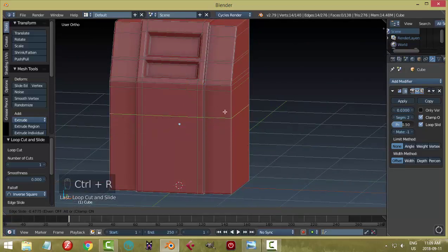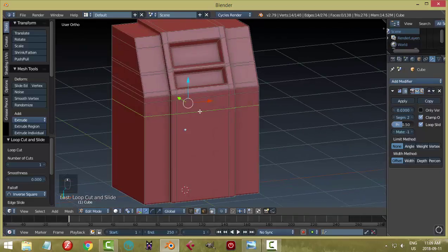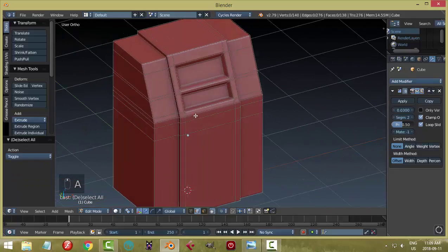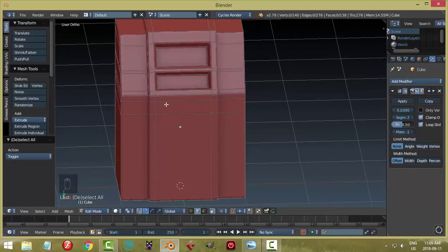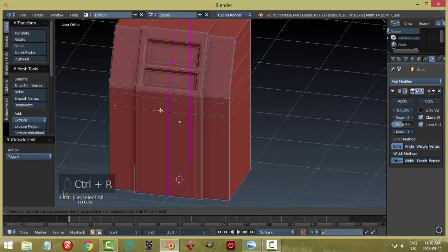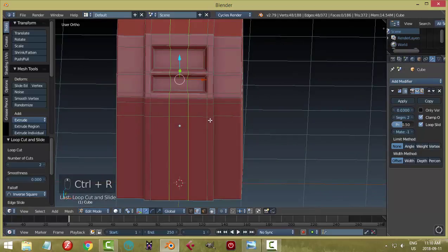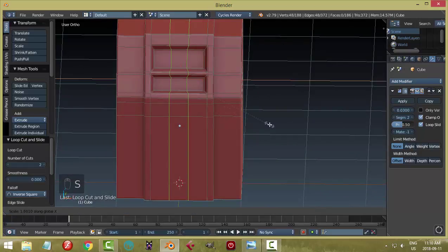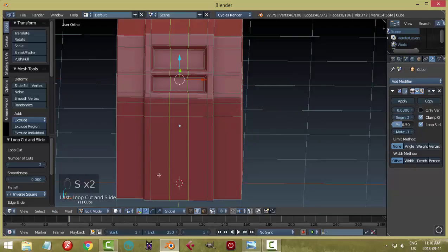Let's go Control R and put another one and define the height of this thing that we want the money to come out of. It might be a bit exaggerated here. So we're going to have a space here, but I want to have a little partial rectangle that goes all the way around, then a little hole. So I'm going to go Control R, roll my mouse up. I'm going to get 2 edge loops, SX. Oh, now that didn't work. Watch this. SX doesn't work right. That's because I didn't switch back to median point. I had switched to individual origins, back to median point, SX.